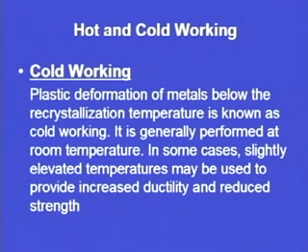What is cold working? Cold working basically is plastic deformation of metals below the recrystallization temperature. So, the plastic deformation is taking place, no doubt, but it is taking place below the recrystallization temperature. As we have seen, the grains are not distorting and too much fragmentation is not taking place, it is below the recrystallization temperature. So, it is generally performed at room temperature. We are not heating the metal to an elevated temperature.